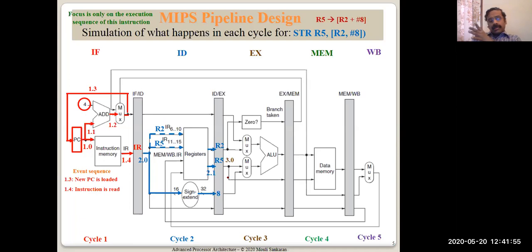It is passed across. If you see that R5 is passed as a solid line, I am showing it because this picture doesn't show like that. Okay, similarly this is a solid line and he is showing it as a 16-bit and 32-bit, so you can understand which is data and which is control signal. So now what is happening, this 32-bit constant is flowing through this. ALU is computing the effective address. It is available during the EX stage.